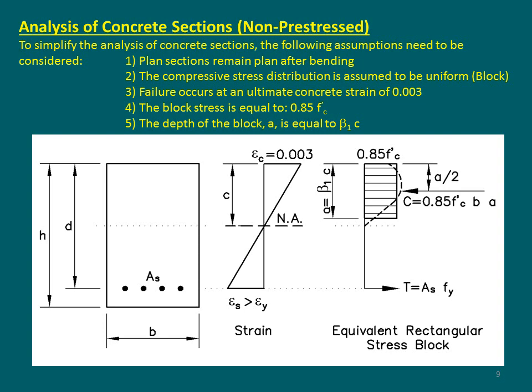The capacity point, as it says in assumption number 3, is going to be equal to concrete strain of 0.003. We understand that concrete, generally speaking, would be able to approach easily 0.004 strain without failure. But according to the code, this is going to be the capacity point.